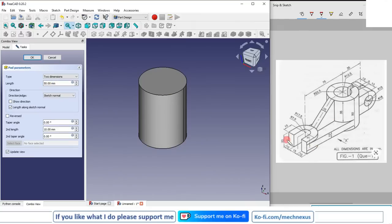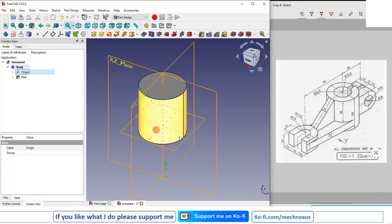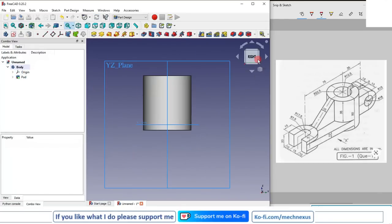So if we read the dimension here, it is a 20, it is a 10, so this is the 5. So in other direction I will give the 5, and in upper direction I will give it 45, and I will say OK. Now I will on my plane. So we can see that it is a 5 mm below. Now we will create this face directly on this plane.